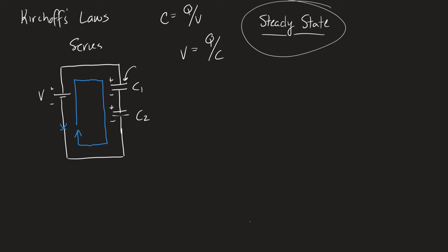All right? Now, Kirchhoff's laws here are pretty straightforward. They tell us what to do. They tell us to create a relationship, and that relationship is just about voltages. It tells me to first start with my voltage source. So I'm doing this in the order that they exist in the circuit. So that's the voltage applied to the circuit, and then subtract any voltage drop. So my first voltage drop is the voltage across capacitor 1.